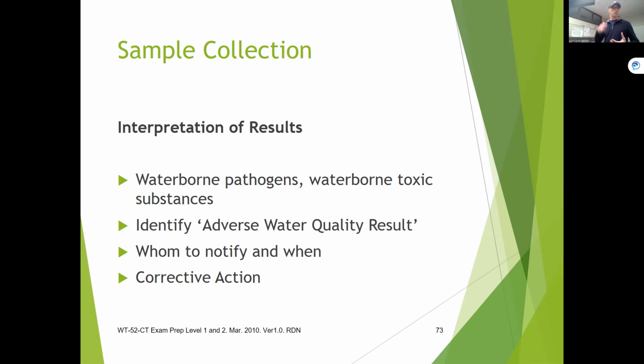Even with the bacteriological, if I get something bad that comes back, the first thing I'm going to look at is, okay, was there a chlorine residual? If there was, maybe there's an issue here. I will always go and resample. I let my health authority know, but then I go back and resample. If it's good, we're good. If it's bad again, then I would take action, whether I flush that reservoir or redo a number of things, but I make sure that things are clean, and then I resample again until I'm happy that the water is super clean.